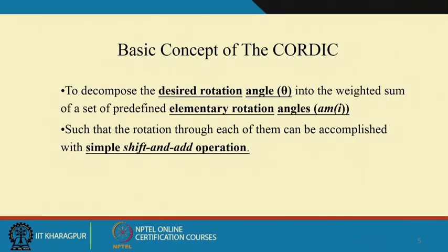The beauty of this is that while we are calculating the sine and cos functions, only shift and add operations are required. I do not need any multiplication, and the operations are much simpler.